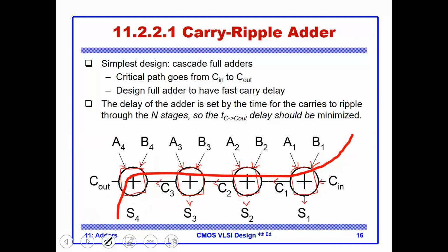Okay, we were adding when Cn equals 1, and the A's are all ones, and the B's are all zeros: 0 0 0 0. Let's see if we get the previous result that we computed. So this is a full adder here, with 3 inputs, 1 0 1. Obviously the sum is a 0 and the carry is a 1.